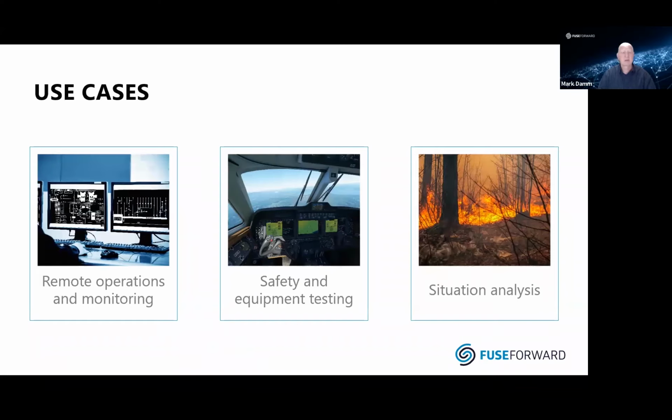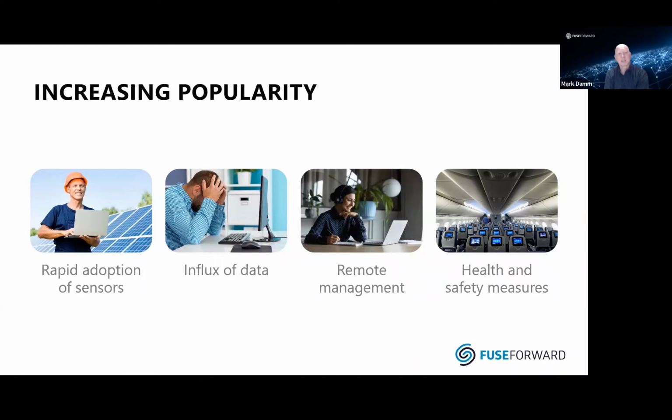Number one, rapid adoption of sensor technology. I've been working with utility companies for 30 years, and we've been working with SCADA systems, analog data controls, and metering systems bringing in data. They're there, but they used to be really expensive. Now they're really cheap. I can put a vibration sensor on a pump and get real-time information about how that pump is vibrating to determine potential fail points and whether the harmonics on the pump are such that it's performing at optimal speed.